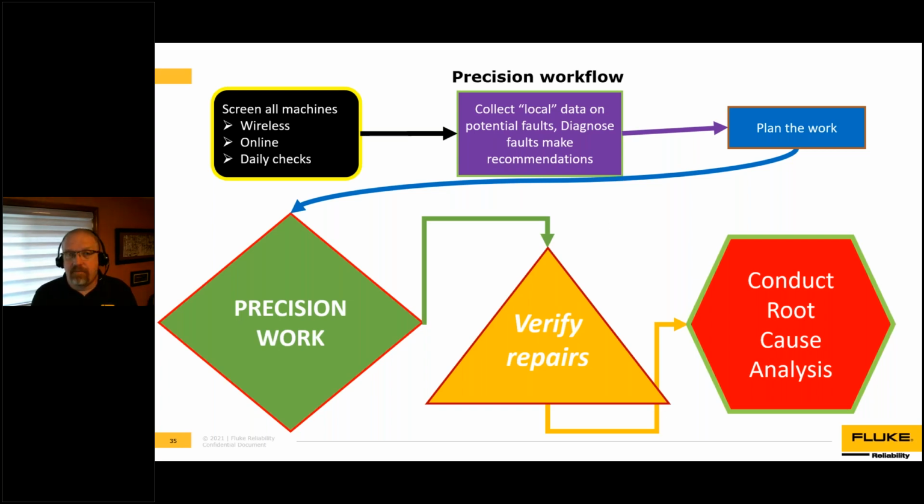Then your vibration analyst goes and collects full spectrum data, and reviews the oil sample data. Maybe do some non-destructive testing, and eventually, once you have identified that something truly is in fault condition, you're going to write some work requests. Those work requests go to the planner.